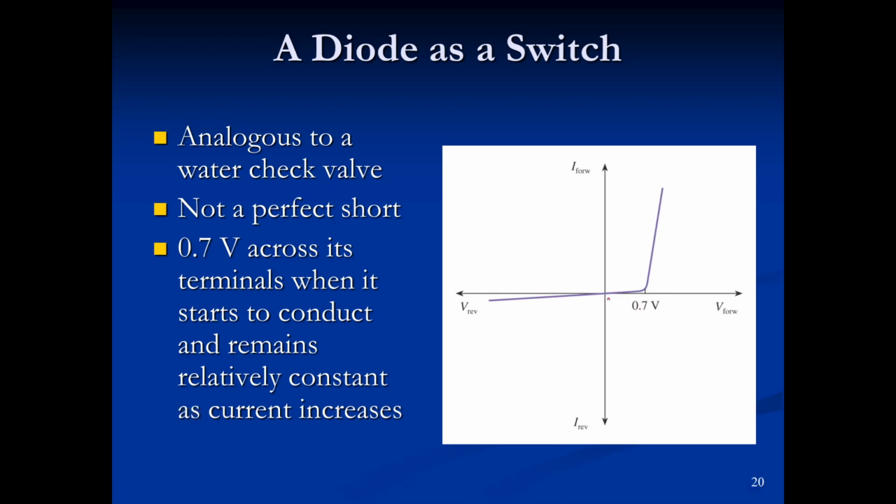If you look at this graph, at the point where the forward voltage, and remember, this is the bias voltage, meaning the voltage across the diode, the anode voltage minus the cathode voltage. Once it hits 0.7 volts and activates, you can keep increasing the current based on whatever other components you have in the circuit. You can keep increasing and increasing the current with a relatively little change left to right. Up here, with this very high current, if you trace the line down, it's still around 0.7, but this voltage doesn't change much the more you increase the current. So we can for the most part assume the voltage drop across the diode is going to be 0.7 volts.